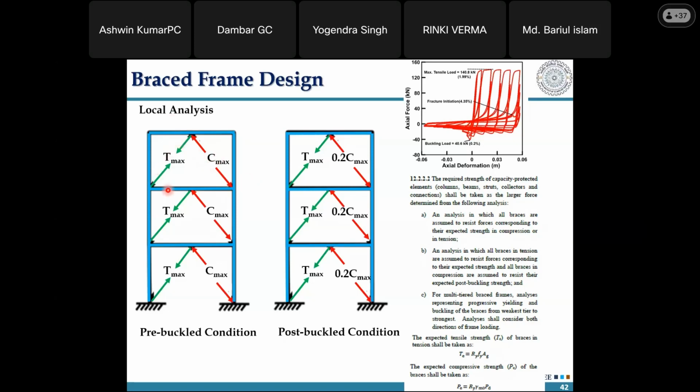So the MRF system is a very low stiffness system. CBF is highly stiff. BRB comes in between with a lower stiffness value. The problem with the BRB system is the residual interstory drift ratio, not just the drift value. If there is a diagonal member, stiffness increases. But after an earthquake, what is the residual drift that is left after a particular event where nonlinearity comes in? The permanent deformation left in the structure at a particular floor is sometimes more than the limit for a BRB system.